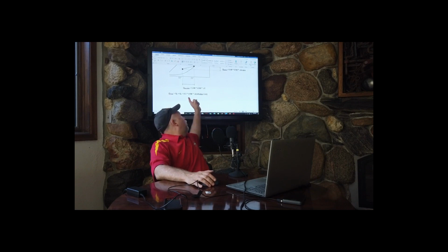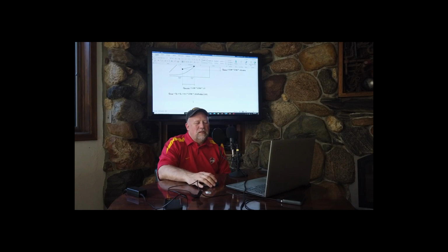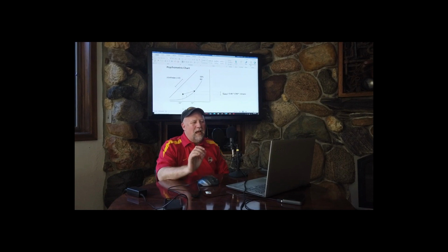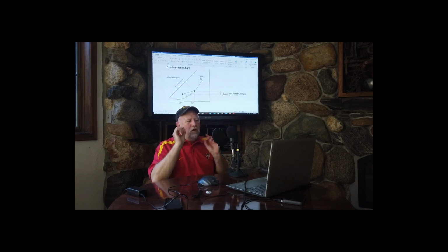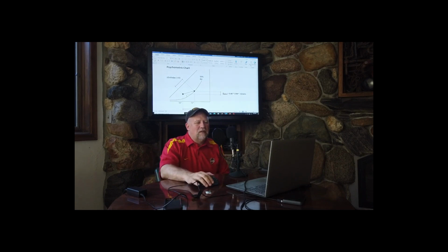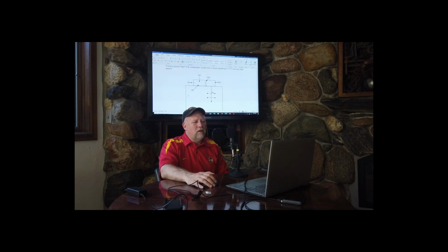Same with 4.5 times CFM times enthalpy, which is in BTU per hour per pound of dry air, right? So those are all constants. Anytime that I give you two different psychrometric state points, you use these equations to determine the difference in energy between those points. How are we going to use this?